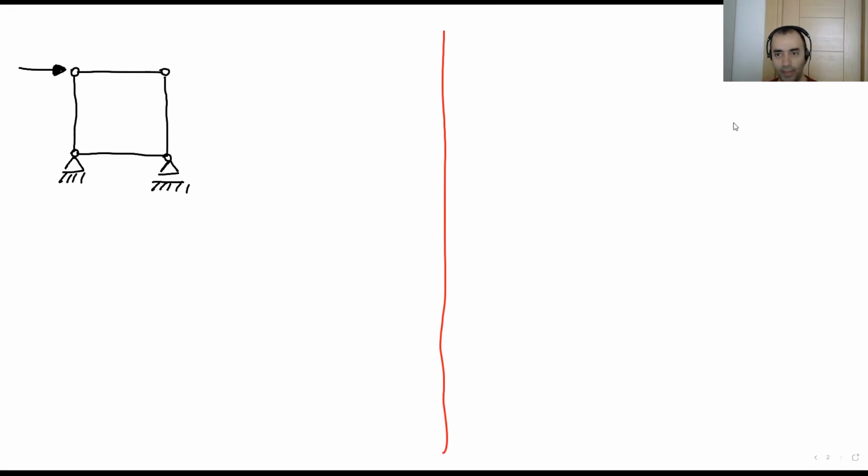She's at the midpoint. When we take a look at this system, each corner here is a hinge. So the other members, straight members, they don't deform. So when we apply this lateral load, it's going to get this shape. Straight members are still straight. This is the hinge point, but there will be some rotations on this.